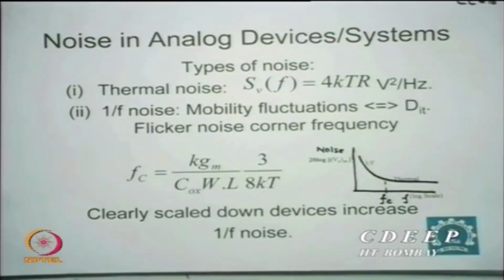All noises are generally temperature dependent. So if you are working on a circuit at higher temperature, 55 degrees centigrade or 70 degrees centigrade, or a military standard requirement maybe 125 degrees centigrade, your noise will definitely be higher. Nothing much can be done because it is kT dependent.